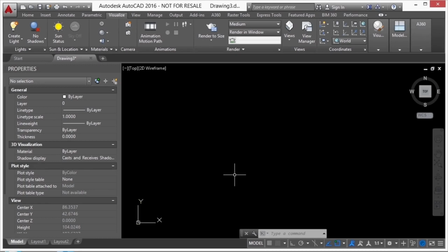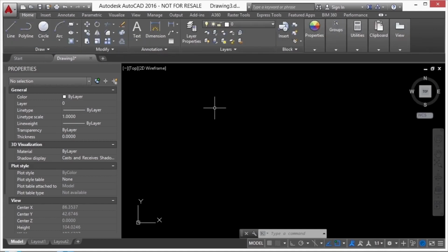Now, AutoCAD has that so that all of our files can work with each other on one system. That 0,0 is just an arbitrary point, but whenever we use it from file to file, it keeps us relative to each other in our locations. That really only comes into play when we're inserting other drawings into drawings, creating blocks and copying and pasting them, or when we're XREFing other files. They need a base point of reference, and the world coordinate system is what we use.